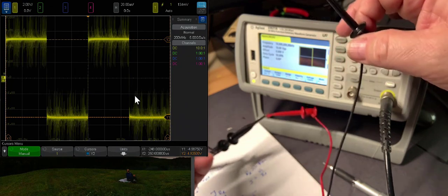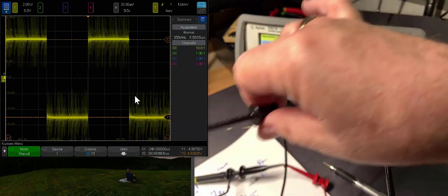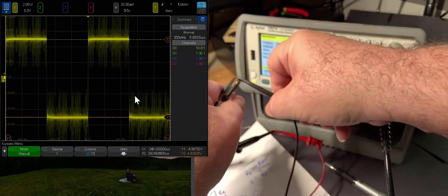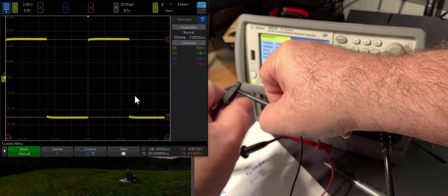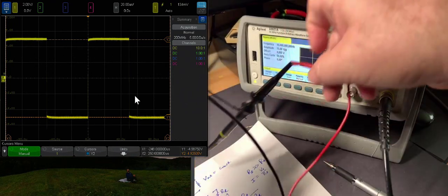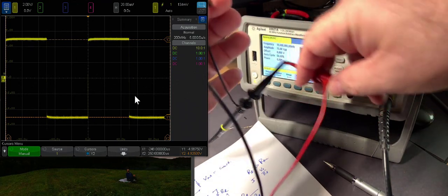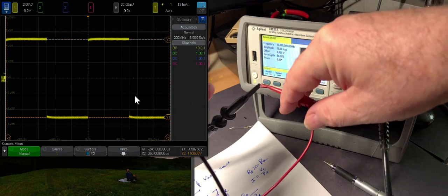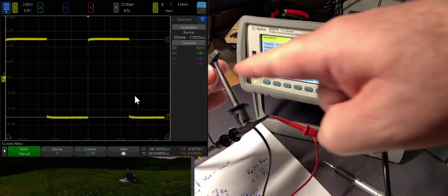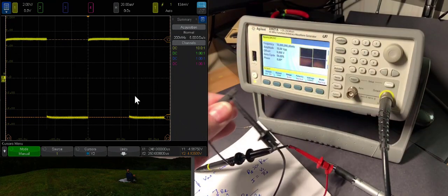It's a really long path. We've made a whopping big antenna, and we're really sensitive to RF pickup in the environment. And that's why we always want to make a good connection here so that we eliminate that large antenna. We still have a bit of an antenna here, and we saw the impact of that giving us that higher inductance in series. Still causes a problem, but for these measurements we're going to live with that so that we can separate out the signal ends and connect a resistor across those ends.